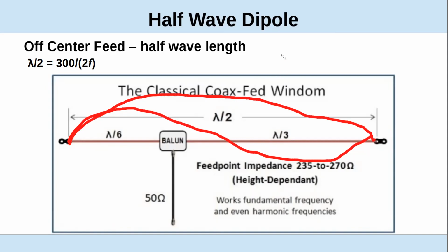So when you grab your antenna and want the minimum RF burn, do you grab the middle or the end? It's a good question because the end is very high voltage and no current until you grab it. And then I suspect the high voltage is going to create a current through you, and what they call an RF burn, which is bone deep.